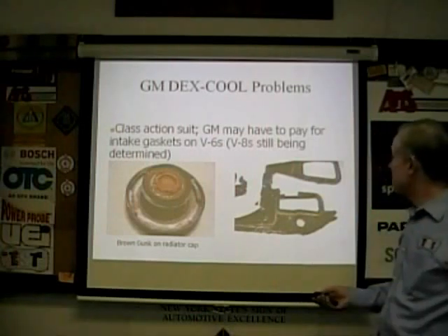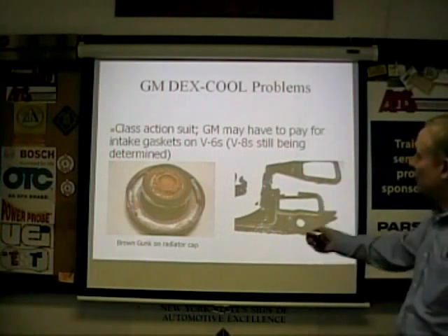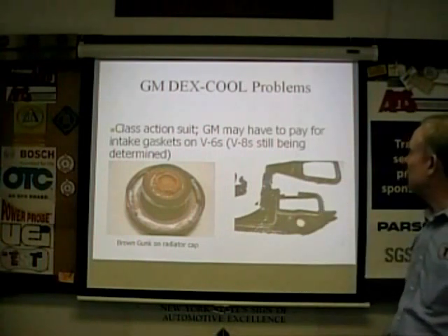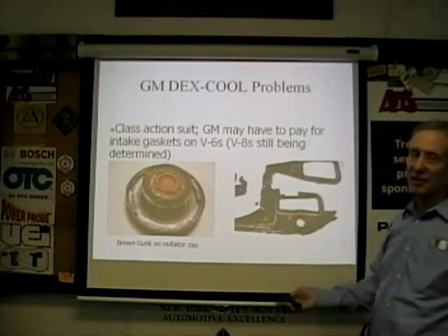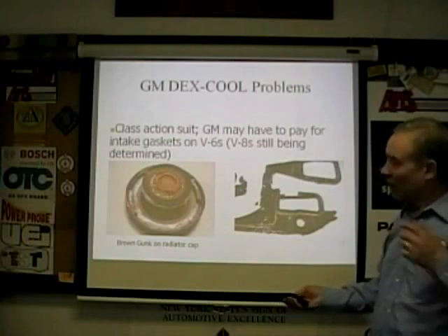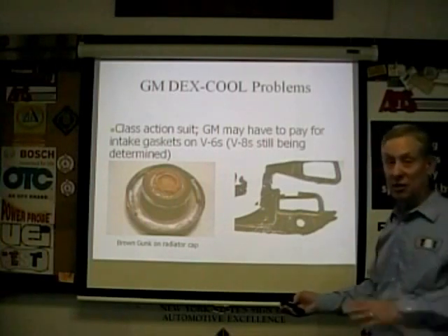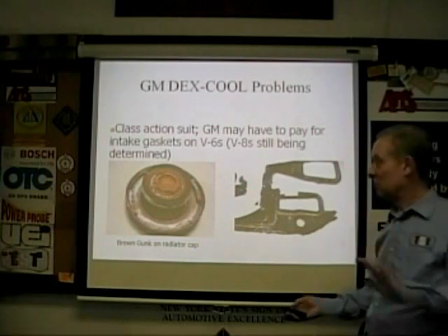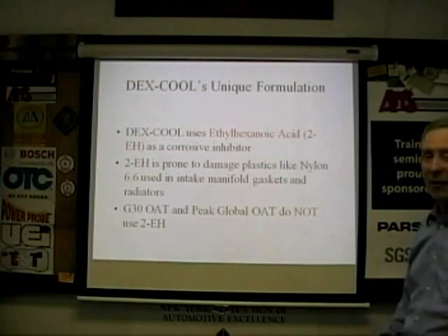Just like you have up there too. There you go. There's a rotted gasket, you know, so forth. There's a class action suit. GM may have to pay for intake gaskets and so forth. But this is only the tip of the iceberg here. Bottom line, if one comes your way, you have to protect yourself and tell the customer you have to do the whole job. I don't mean to sound like my way or the highway, but it's my way or the highway.